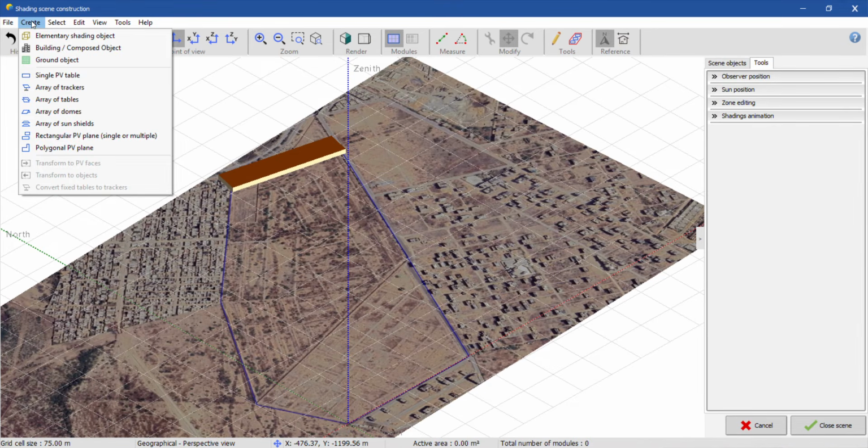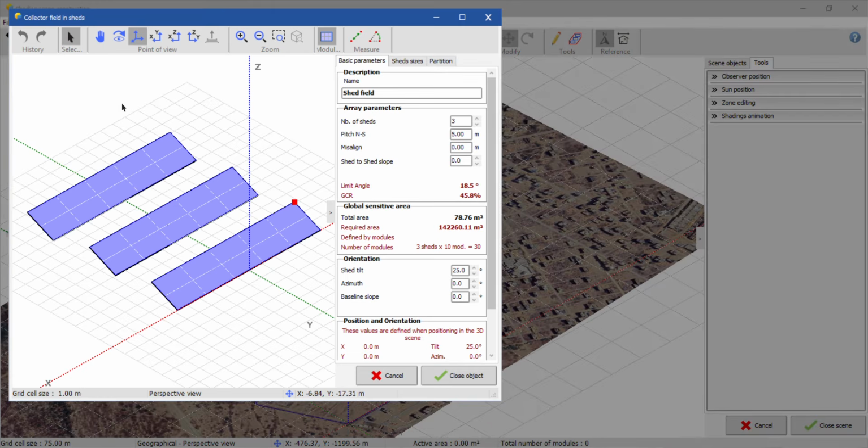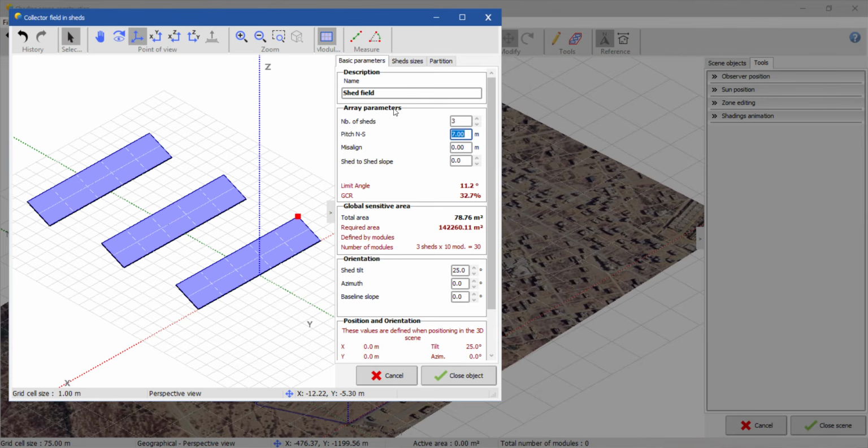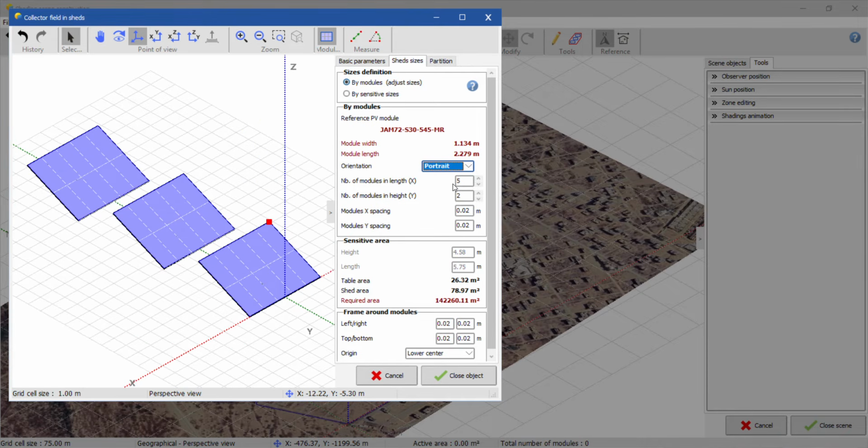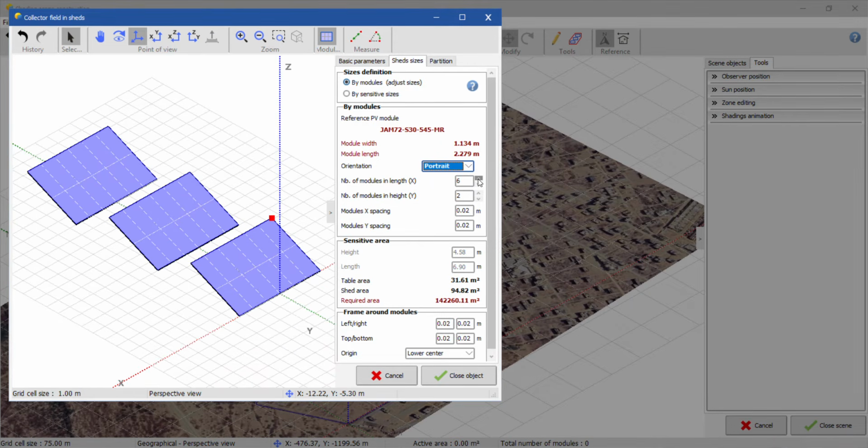Now you have to select a shading table from your system. You will assign accordingly. As I previously mentioned, we are using at least a 7 meter pitch from shading to shading, and the panel orientation depends on your case. I prefer landscape. Are you going to use portrait? It depends on you. I think we use portrait most of the time, but it depends on your case.